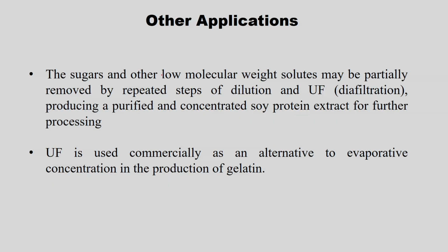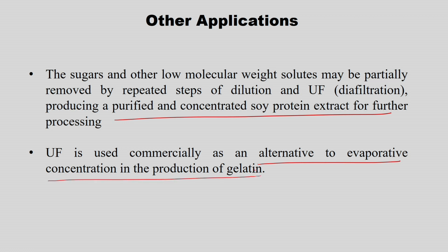Also, sugars and other low molecular weight solutes may be partially removed by repeated steps of dilution and diafiltration, which produces a purified soy protein extract for further processing. And ultrafiltration is also used commercially as an alternative to evaporative concentration in the production of gelatin. So, these are also included in the ultrafiltration applications.